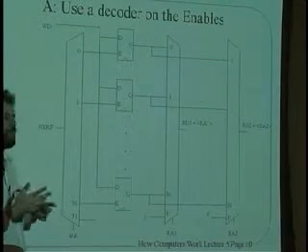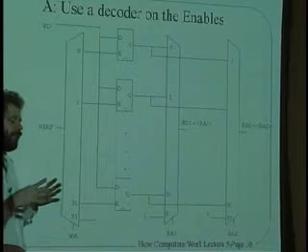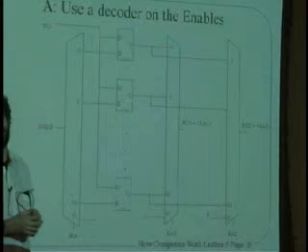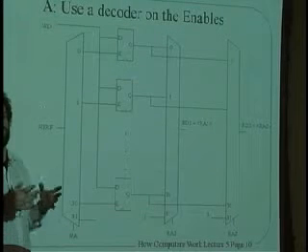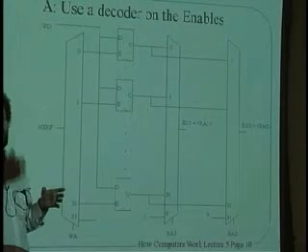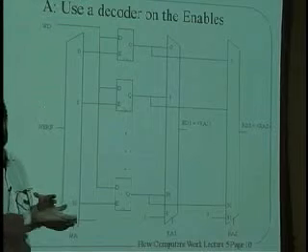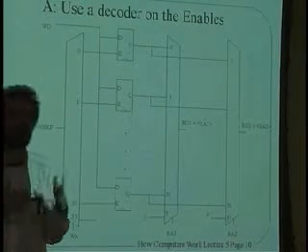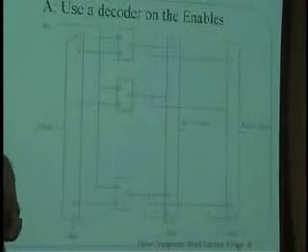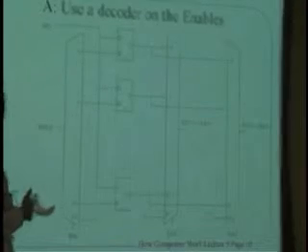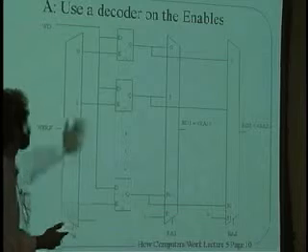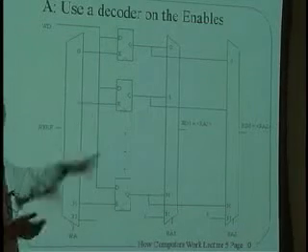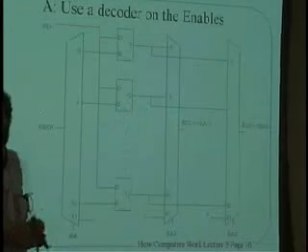But most programs and the instruction set architecture that we've designed is one that really only writes to 1 destination at any given time. The opcodes always operate on RA, RB, putting the result into RC. So there's really no mechanism for saying I want to write more than 1 register at any given time. But you're right, you could design this in a different way where you did not use a device like this, but instead had 31 separate wires, of which more than one of them could be on.